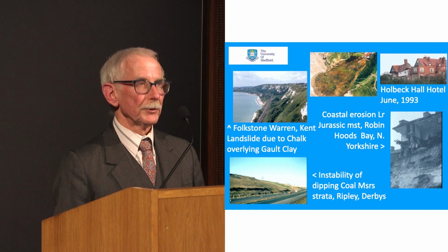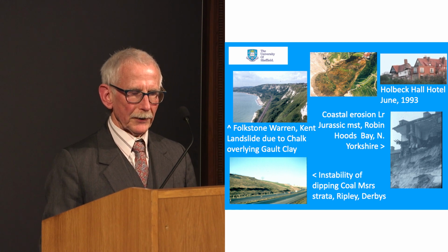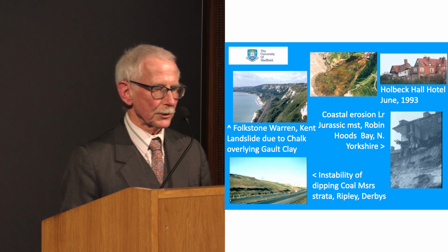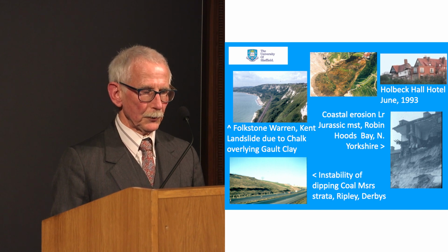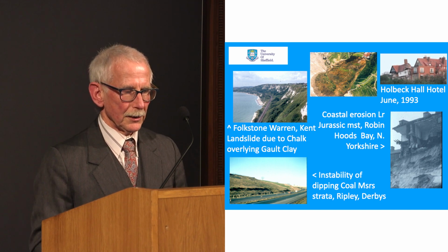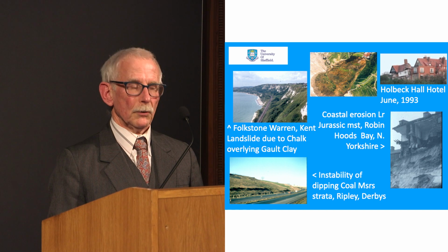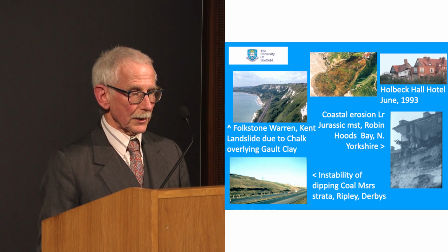Sometimes problems occur in underground construction, where excavatability of the ground and the support of the excavation are important. Some mud rocks contain stronger materials that can be difficult to excavate, so unsuitable methods of excavation are used, or the support for the ground is inadequate, leading to the collapse of the excavations, or even worse, where it reaches the ground surface.